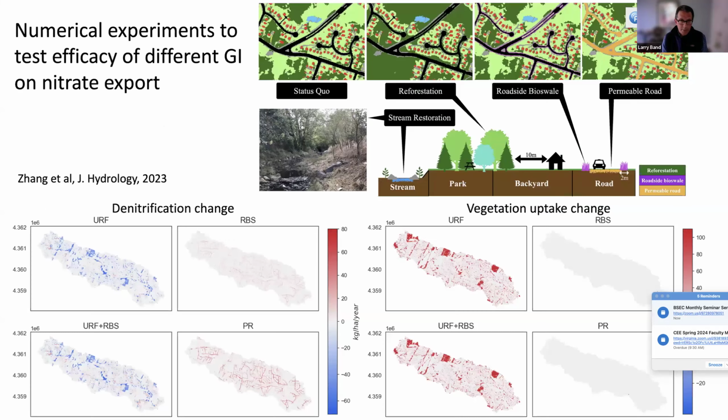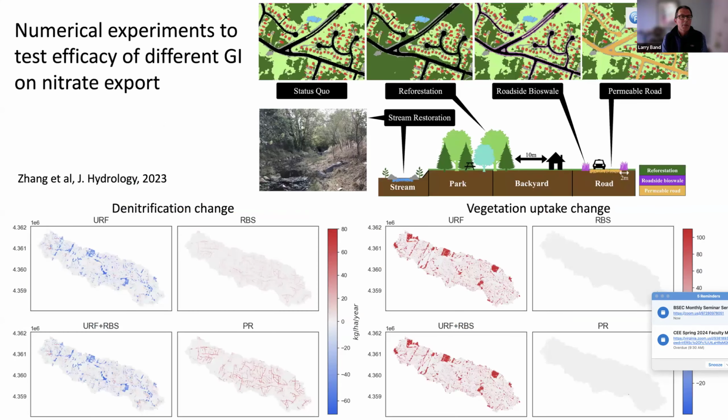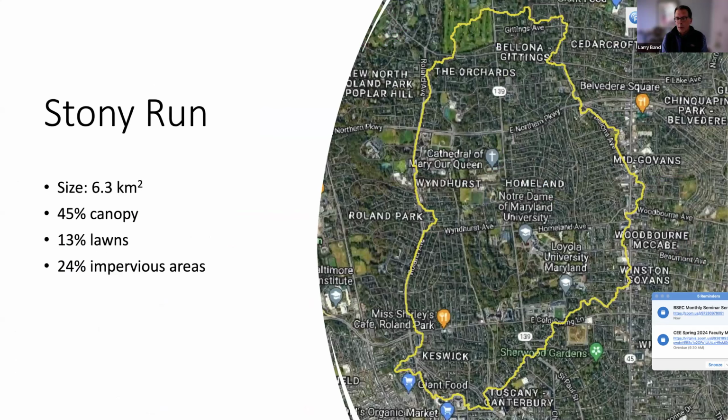Scott's Level Branch is 8 square kilometers. We're simulating this, I think, at about, Roy could tell us, but I think at about 15 meters. By the way, those grid cells can have multiple forms of land cover. Walk out your door, you have a meter wide path, you have a little bit of lawn, you have a street, you have a more extensive lawn or rubble, and then a rooftop. So within 15 meters, you have a lot of different types of surface covers. So this is subgrid variability in the surface cover that may be sharing a soil resource.